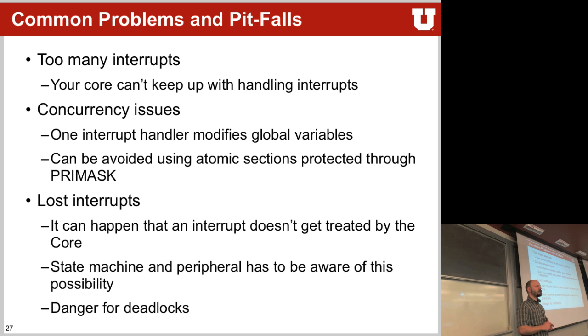Yes? So if you're masking interrupts, do they just sit in the pending state until you say, okay, I'm ready to go back to them? Yes, exactly. They just wait for you until you re-enable them. Because then it looks at which are all pending, and it will start executing.